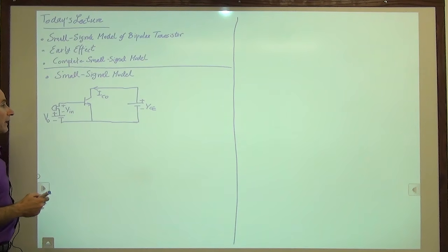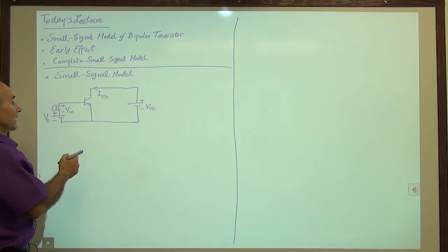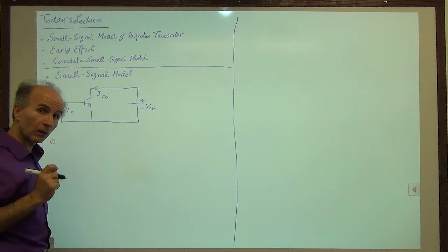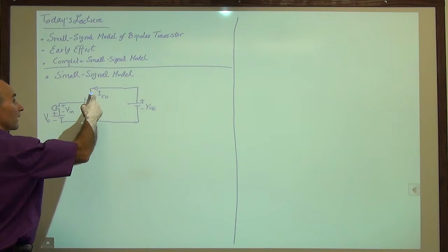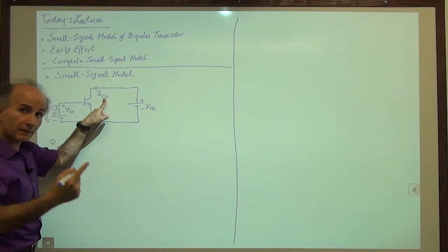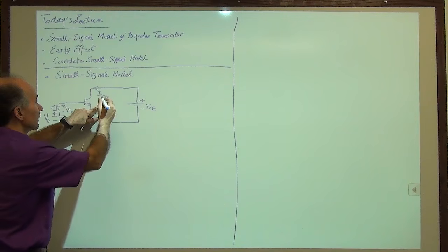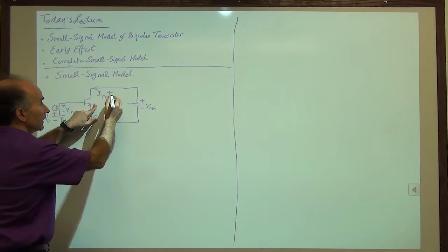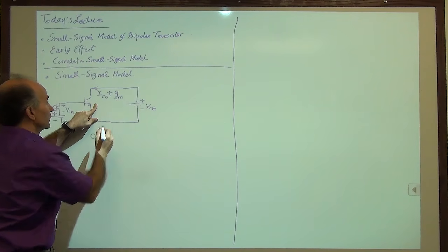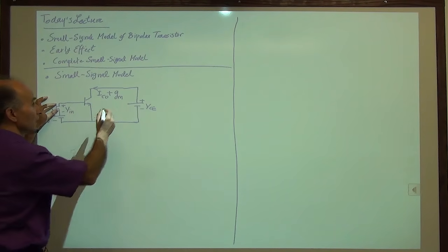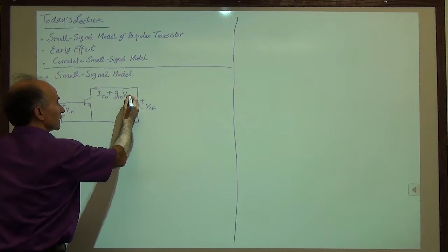Okay. All right. Now what we noticed was that when we apply the signal here, and the signal is small, the collector current is equal to the original current in the absence of a signal plus Gm of the device times this voltage that we have added on top of the bias, provided that this is a small voltage. So Gm times Vin.